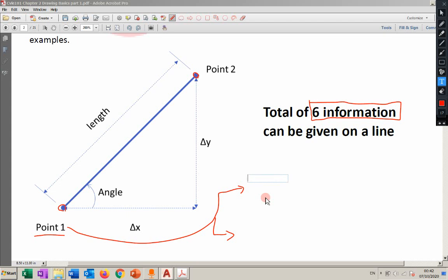So left click is basically providing, when you left click, it means that you're giving a point to AutoCAD. This is one way. The second way to provide a point is coordinates. Now, coordinates basically means x and y, referring to the origin. Remember, we said that in AutoCAD there is an axis which is the origin. Anything refers to that one; we have different coordinate systems. We will come back to them as well.